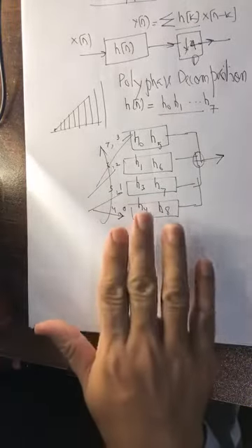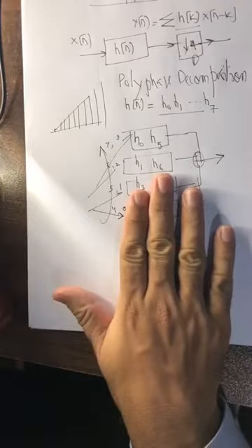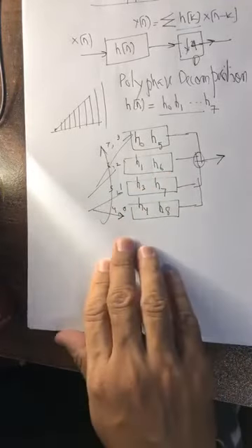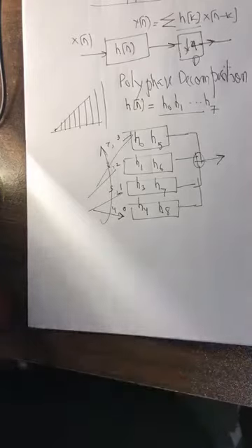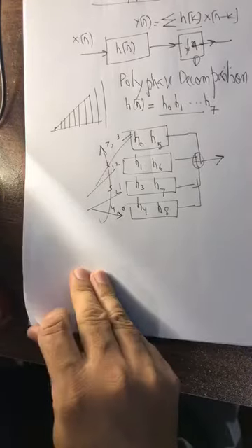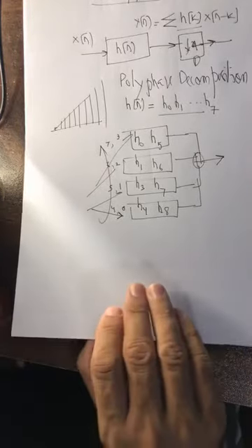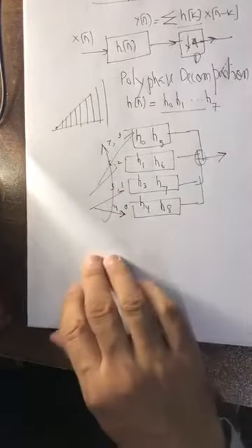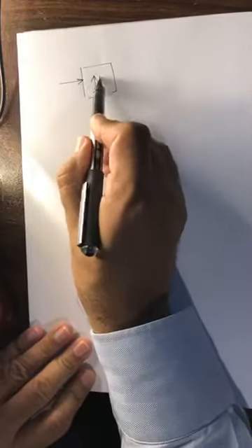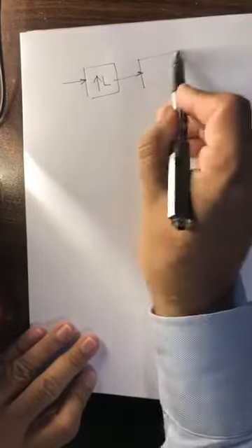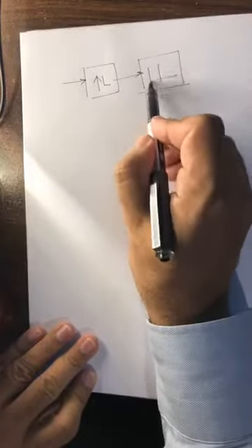The code which we have provided you has this example where the filter is divided into 2 parts and the signal is divided into 2 parts, and it shows that the decimation, this and this are equivalent. Same is the case with interpolation. In interpolation, as we have discussed, first you insert zeros, then you pass it through a pi over L filter.